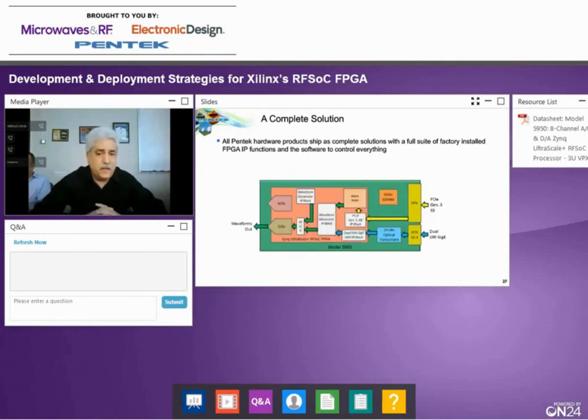The second slide is the D to A direction, and I didn't animate this one, but basically we have paths. You can bring data into the board, go into the onboard memory and put waveforms in there. You could create a waveform table and then have the waveform generator IP send that out to the DAC as required. You could do it with triggers. You could have multiple waveforms in there. There's another path to bring data in through the 100 gig E.